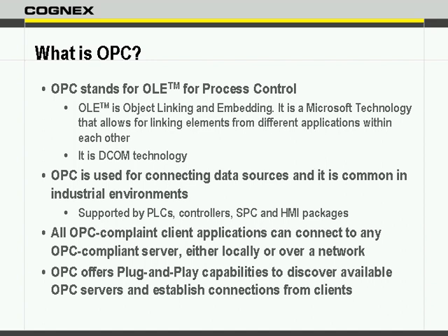OPC is supported by many industrial devices, some PLCs, controllers, SPC and HMI packages, etc. And the idea is that OPC is a common framework and a well-established format for transferring information or data that will bring together different applications.